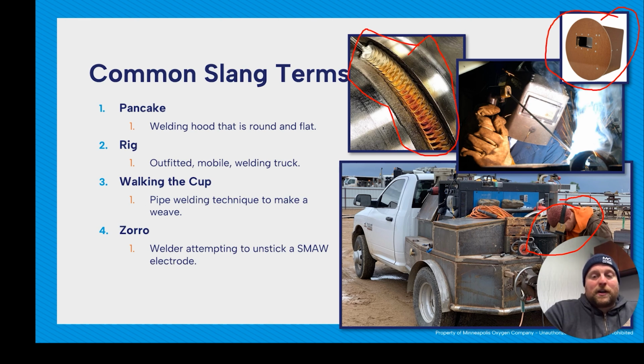Things like walking the cup and techniques like that are very useful in some industries. I know pipe fitters, very useful. Great to make a very nice looking cover pass. But one thing you just need to be aware of is the more you manipulate your electrode, the more you move it around, the more you will affect your penetration. Doesn't mean you're doing something wrong, doesn't mean the weld won't work, but just be aware that the more we're moving our electrode or our torch from side to side, we are going to be affecting our penetration to some extent.